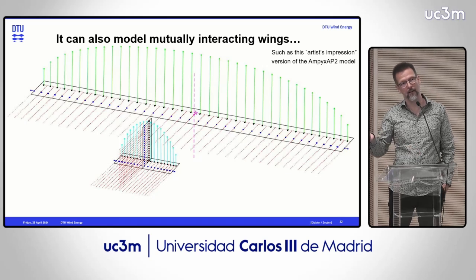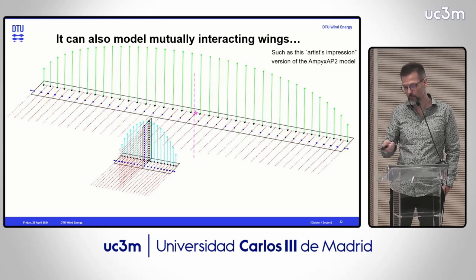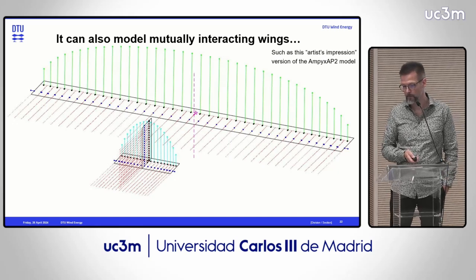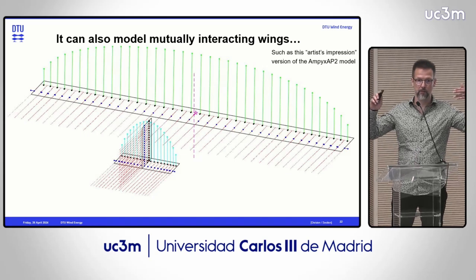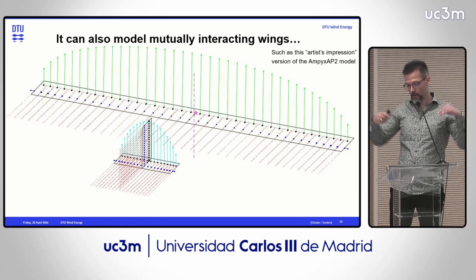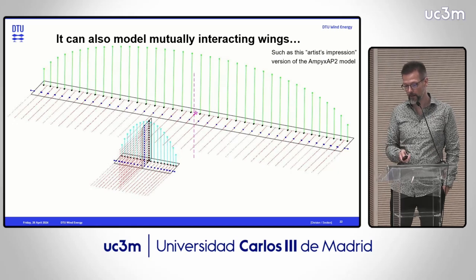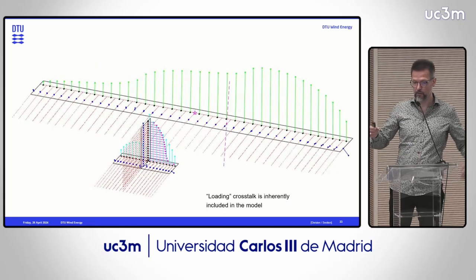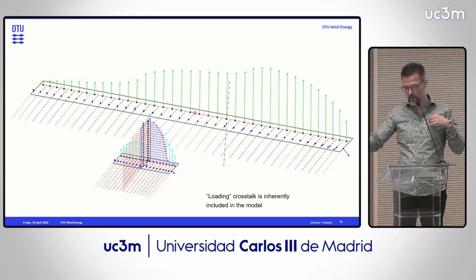I got data on the main wing, but I really didn't get data on how the tailplane looks and what the airfoils are, so it's something I guessed from pictures. So this is when the wind comes from straight ahead, and when I then start to flap the ailerons and the vertical wing at the back, you can see that the aileron changed the loading on the main wing, so I get more load on one side and less on the other.